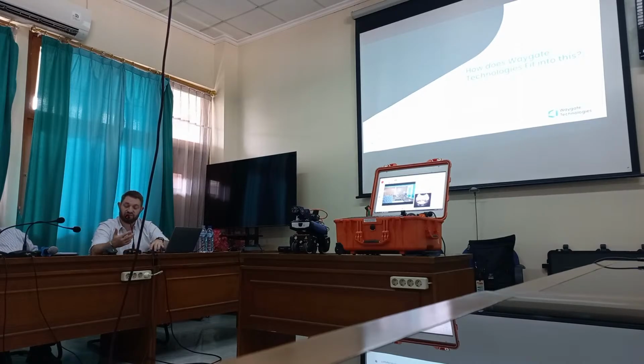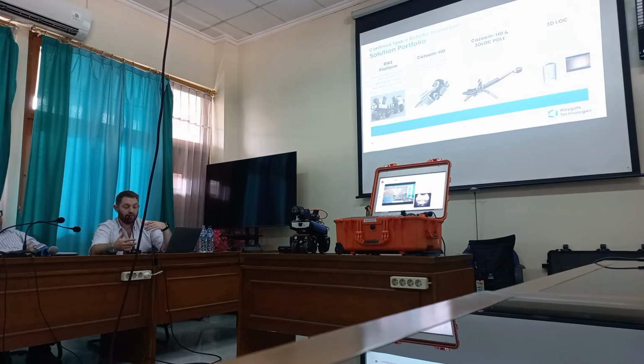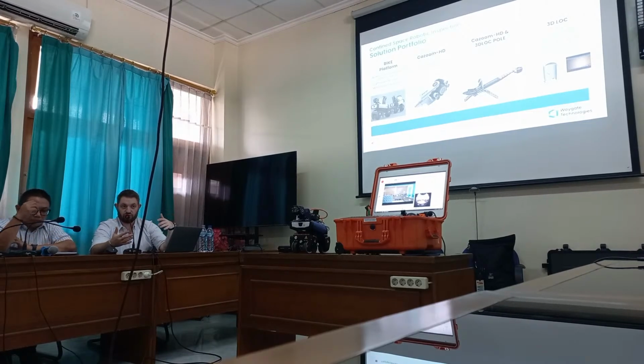Within our technology portfolio for our robotics team, we've got our bike platform, which is just in front of us. This is an ultra-mobile robot that is a delivery platform. It is designed to navigate through complex environments, through different types of structures and geometries. We can transition from horizontal to vertical and back to overhead again with the magnets and the way that the robot works. We have the new Zoom HD, which is a large space or large area visual camera, for doing large pressure vessels, storage tanks, gas spheres, things like that.